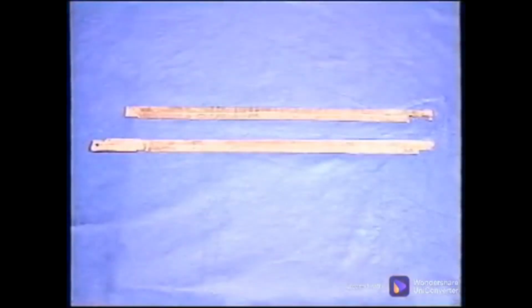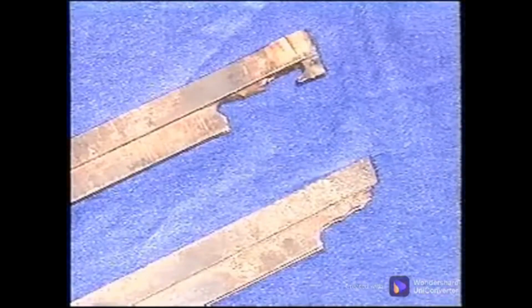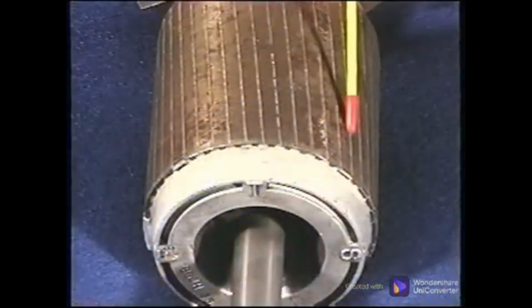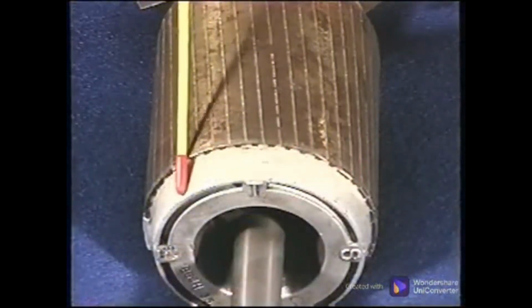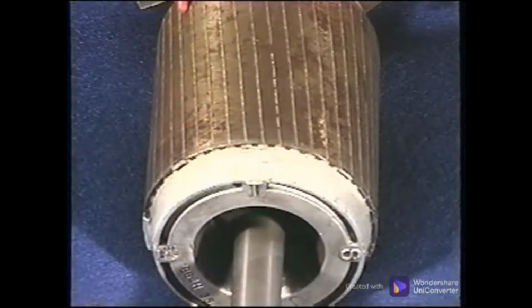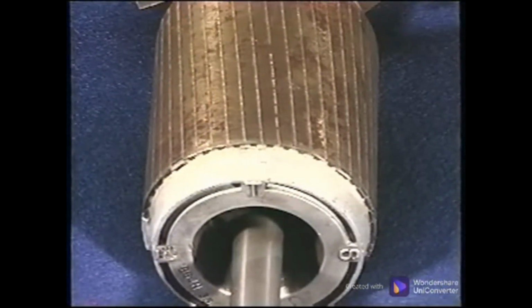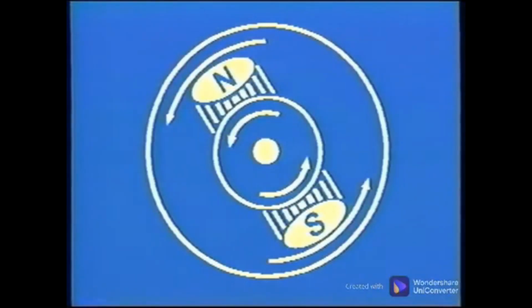The rotor bars can develop cracks or even break in two. Since the rotor bars carry current to the end ring and to another bar, the crack or break affects more than just one bar. Since it is not carrying its load, it causes small changes in the rotor speed as these bars pass the stator poles.